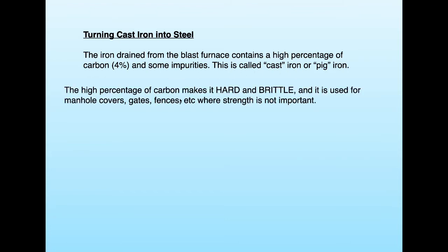Because of the high percentage of carbon, it's hard and brittle. So it's used, if it is used, in contexts where strength is not that important, hardness is. So manhole covers in the street, gates, fences, etc., where it doesn't matter about the strength as much.